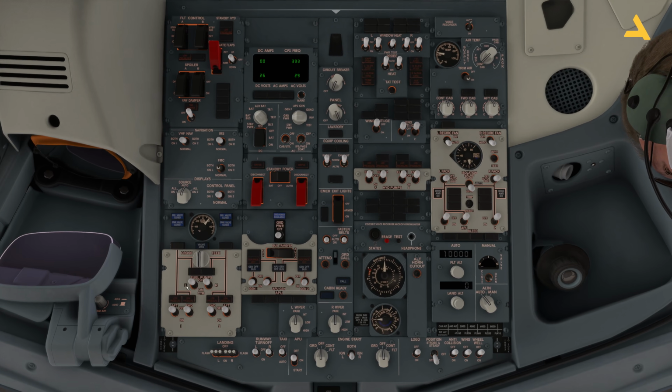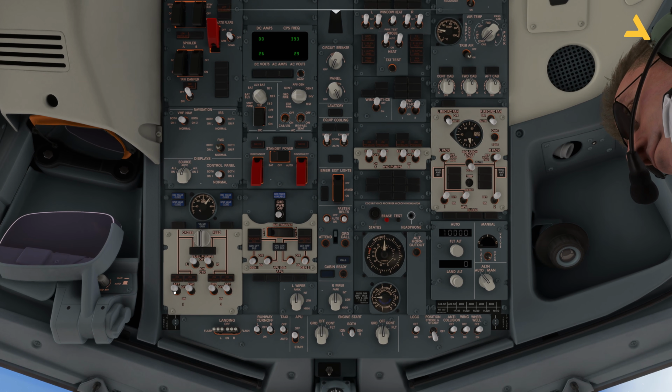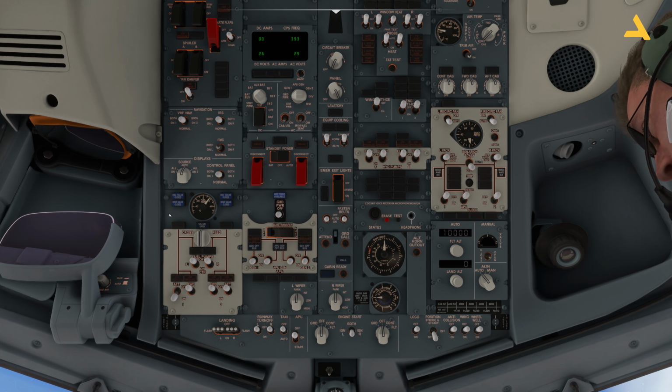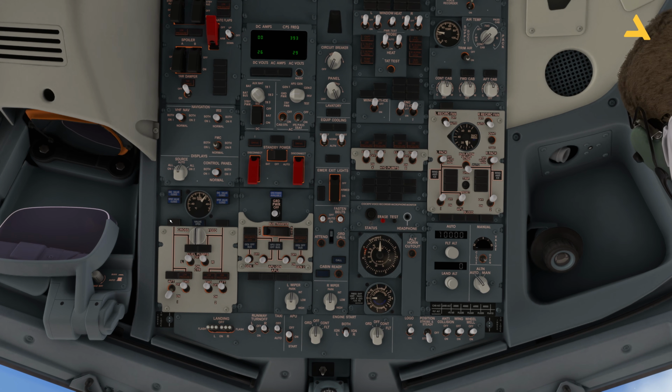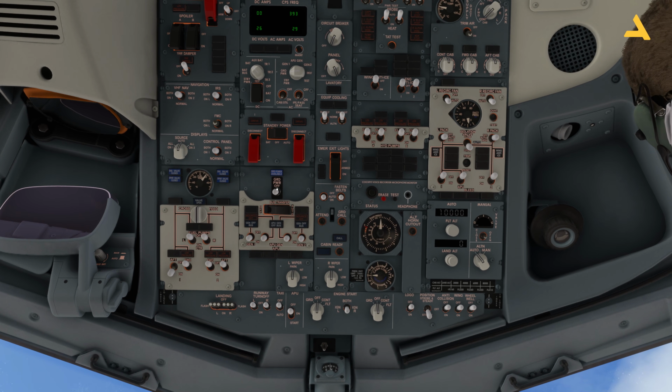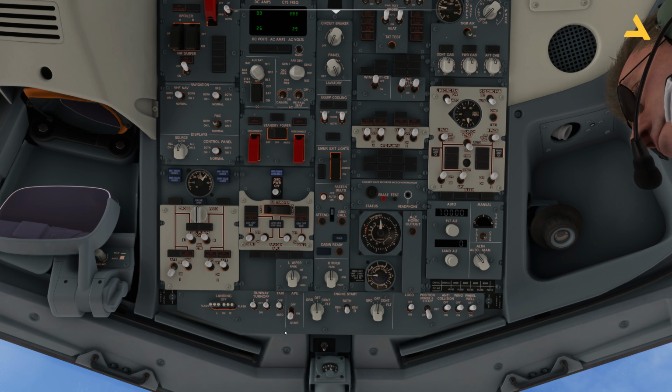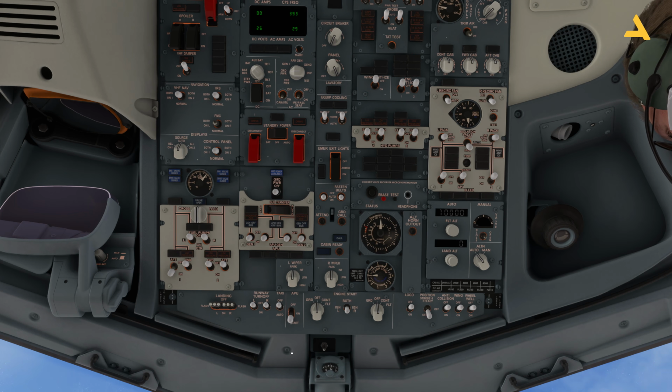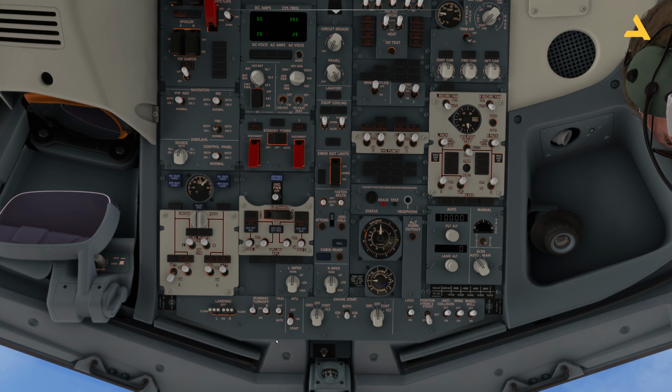Now turn on this fuel pump, this one for the aft, and now it's time to turn on the APU because now I will be proceeding with this pushback. So that's why I have to disconnect the ground power. But for this, we should have some power in the plane, and APU provides this power till the time the engines are on. Now this switch, just move it to start and then just leave it. It will go back to on again, and now the APU will start.